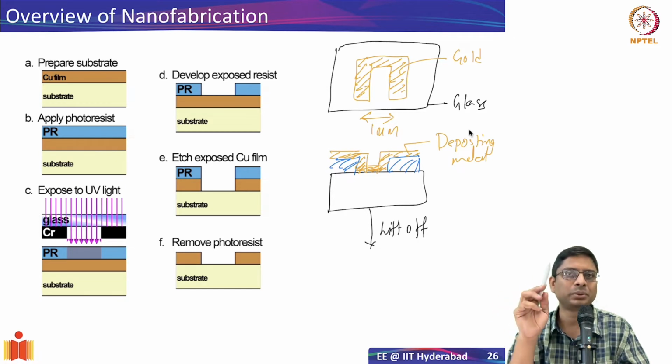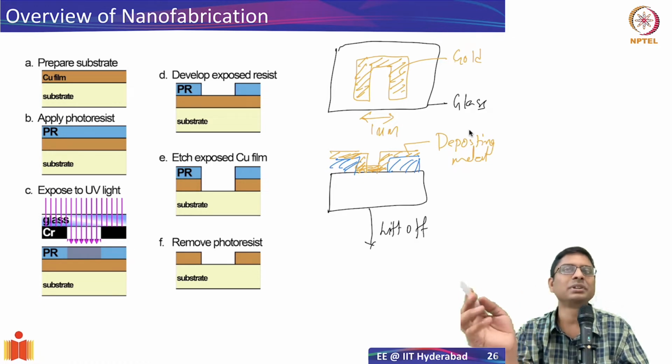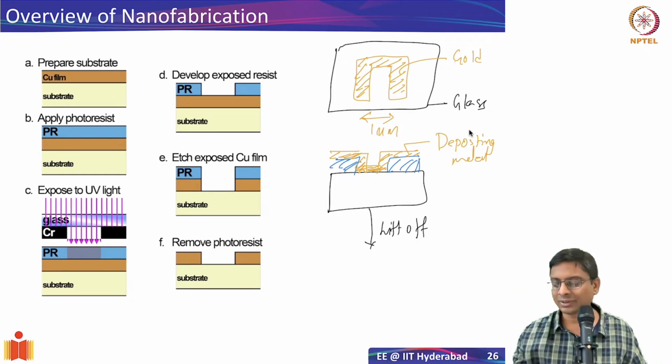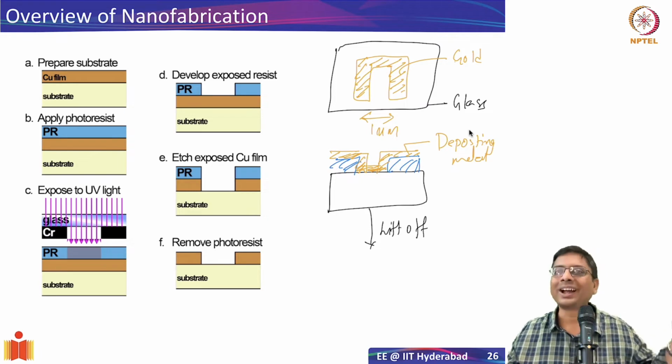Wherever you don't want the paint, you'll have a paper, right? And then simply dissolve the paper and you get left with a pattern. So in spray painting, you're essentially depositing the color on the wall. Similar, just with some mask, right? Similarly, you can make a mask out of photoresist. You deposit everywhere, and then you simply remove the paper by hand. Here you have to dissolve the paper. Again, putting water is enough to dissolve the paper out. So you are left with something which is solid.